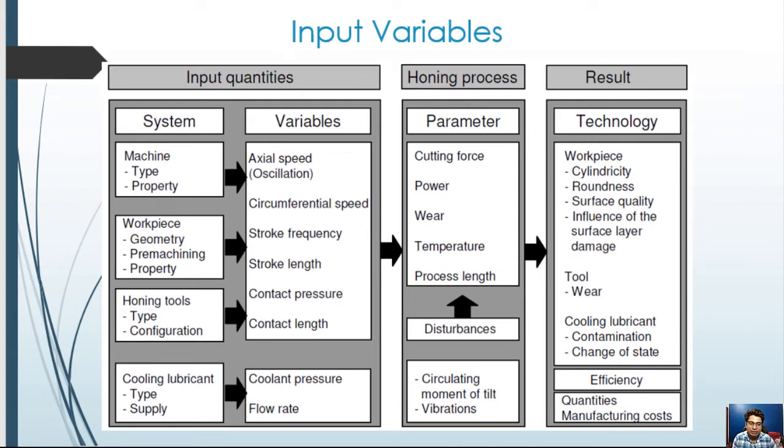The variables determine the possible system mechanics and kinematics of the process. The kinematics results from the superposition of two movements: axial movement comprising the axial movement of both the tool and the workpiece, and rotation of the workpiece or tool in the machining of cylindrical surfaces, or transverse movements in machining of level surfaces.